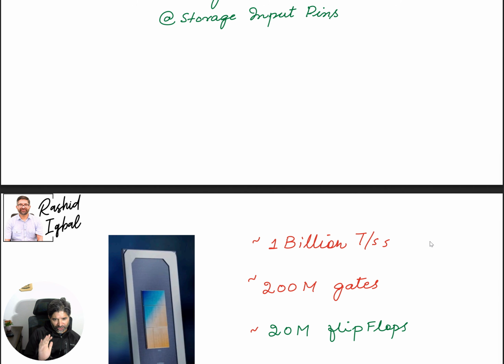But let's look into a chip with 1 billion transistors. As I said, modern chips will have many billions of transistors, but take 1 billion. Then, what is the equivalent in gates? In physical design, when we do the layout and all that, we talk about standard cells, gates. So what is the gate count for that? A gate is typically a NAND, right? A NAND has 4 transistors.